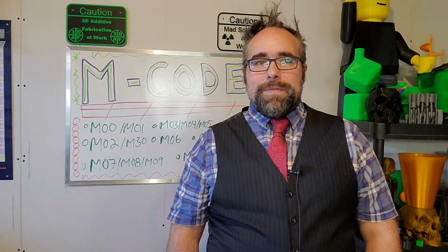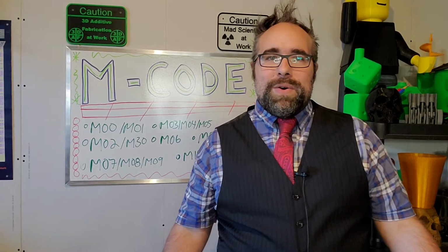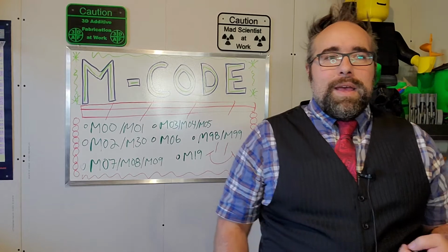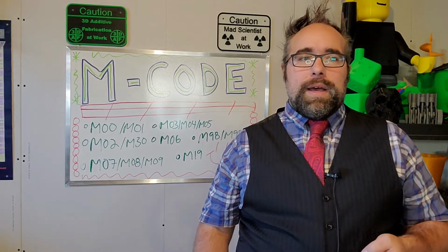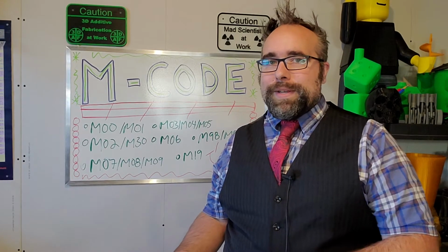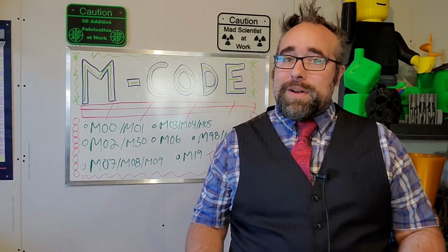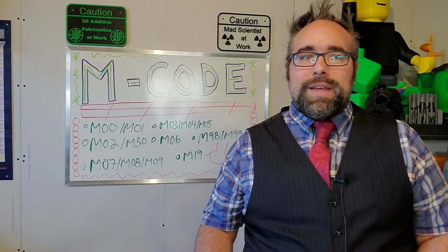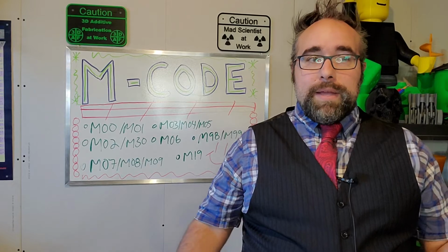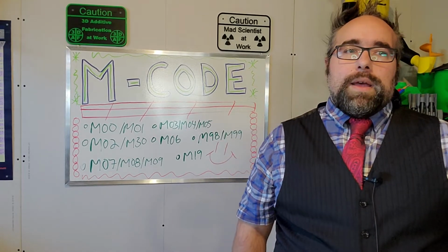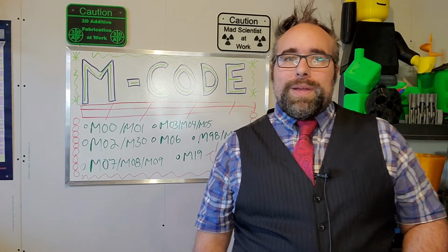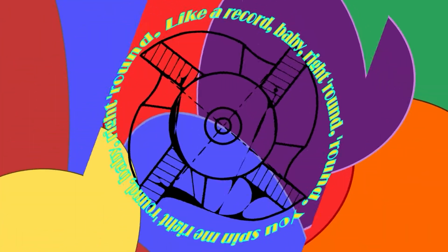And now, the moment you've all been waiting for, spindle codes! That's your M03, M04, and M05. Spindle codes tell the machine how it's going to utilize the spindle, so this is more important in machines that have spindles. Obviously, if you're running a 3D printer, you're not going to use this one as much. These codes are typically used in conjunction with the S, or speed, or RPM, spindle speed word, with an accompanying value. So first we've got M03, which is clockwise spindle rotation.